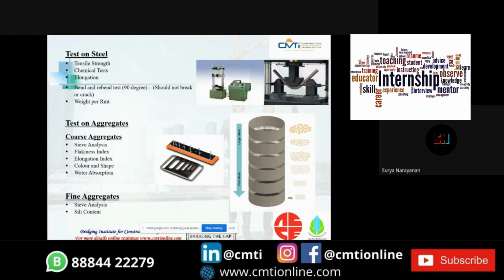So, tests on aggregates. There are two types of aggregates, namely coarse aggregates and fine aggregates. Coarse aggregates are those above 4.75 mm, and those below 4.75 mm are called fine aggregates. The tests to be carried out on coarse aggregates are sieve analysis, flakiness index, elongation index, color and shape, and water absorption. Sieve analysis, as you can see in this image, is where the sieves are arranged in descending order and the aggregates are collected in different sieve sizes. It can be done either manually or by using vibrator machines.